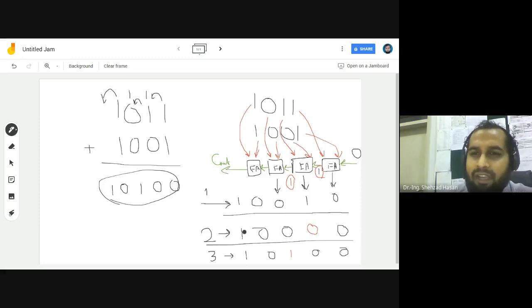Whenever we design any circuit, we always consider its worst case time. So that's the problem with ripple carry adder, that the worst case time of that adder is high, right? If it's a 32-bit adder, it's going to give the result in 32 steps. That's the maximum delay that's going to happen.